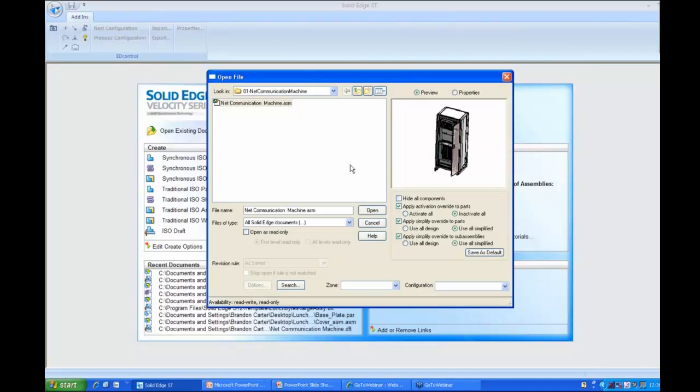If you think about it, this would be the lightweight format to open the assembly. All the parts are going to be inactive. What I mean by inactive and active is, and I'll show you in a shortcut menu shortly, activated means that at the assembly level, we have all the part geometry, how the faces are, all the math behind those faces loaded to memory at the assembly level. If we have them inactivated, that math behind those faces is not loaded at the assembly level. However, you notice that your constraints and you physically see the part, and as far as your assembly, how it's constrained, how it's sitting there, that's not going to affect anything.